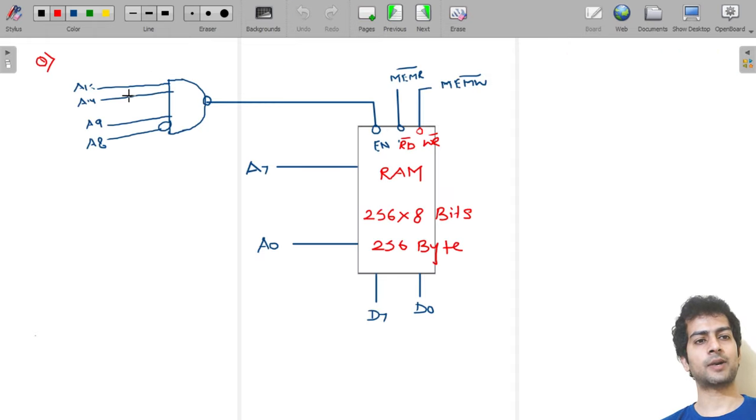Now, this part remains the most important thing where you have to apply your brain, and depending on this only the range of this memory changes. Now see what we have. We have A15 to A8 here, and we have an inverter at A8. So what we have to get is 0 here. When will we get 0 here? We will get 0 when, before this inverter, we have a 1, then only it will get inverted to 0. So we have to have 1 here.